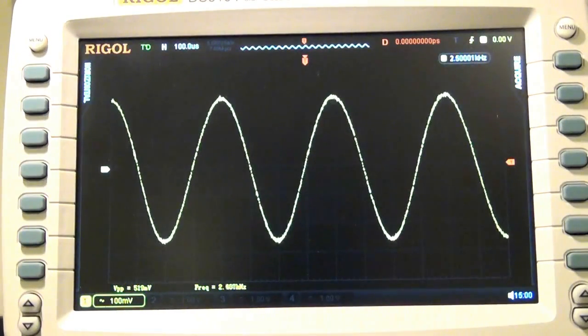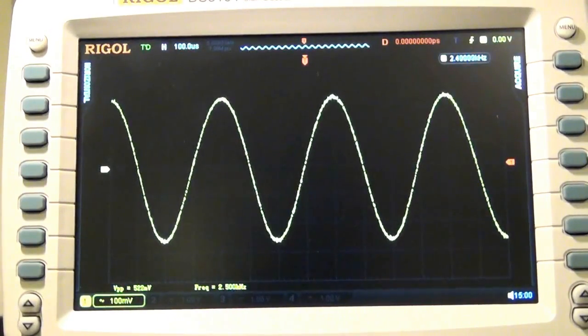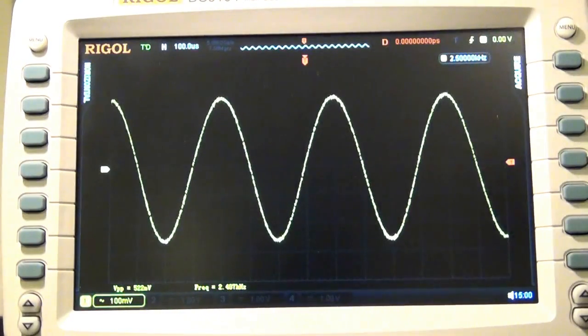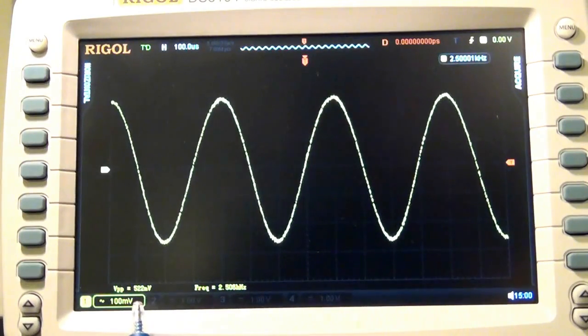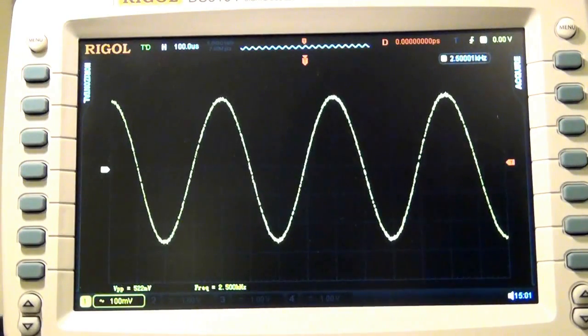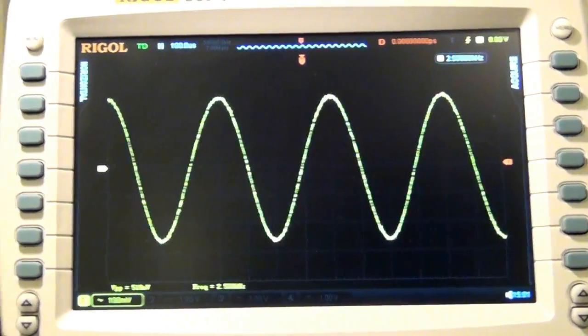Now what is that equal to? I can get my calculator. So 520 divided by the square root of 2, that is 367. So I can increase the frequency until my output swing hits 367 millivolt peak to peak. At that point, I have lost a square root 2 factor of the output voltage swing, which will correspond to a 3 dB reduction in the output gain. So let's do that. Let's increase it until we hit that point.